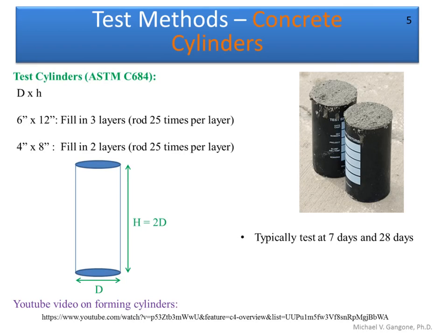And one of the last things that you often will do on a field site is to form concrete cylinders. You either take 6x12 or 4x8 cylinders, and you want to make sure that you fill those with concrete. Eventually, you're going to test the 7 and 28-day strength of that particular concrete and determine if it meets the standards required of the concrete.